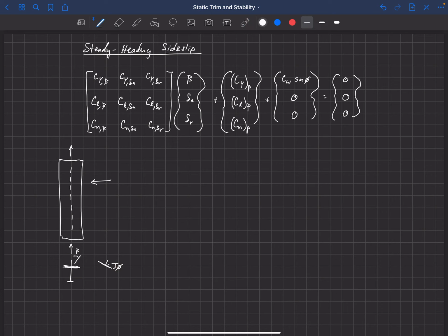Now another option is what's called crabbing the aircraft, and in this case, what they do is they actually point the nose of the aircraft into the wind, so they'll rotate it there. And so the aircraft will still continue to move in this direction, but they minimize the beta that the aircraft experiences. So this is called crabbing the aircraft, and so it's crabbed into this crosswind.